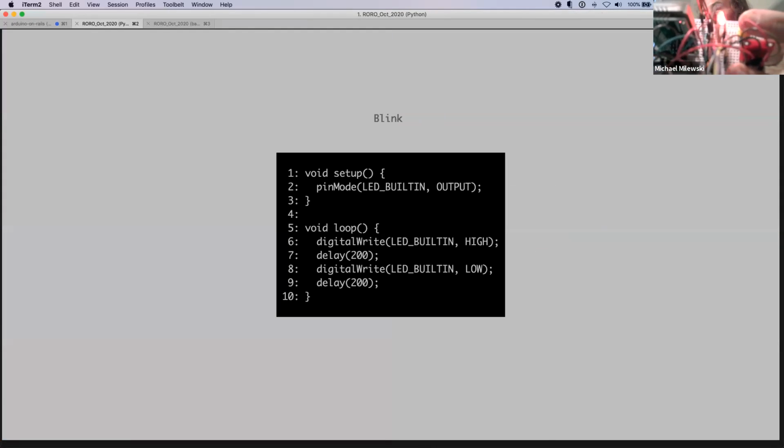So in here, I have the equivalent of the hello world of Arduino, which is to blink an LED. And I can see there's two main methods. The code here is actually C++, although given how small an Arduino is, for all intents and purposes it's like C. An Arduino has two default methods. One is setup, which is called anytime the power is booted, and the other one is loop, which is just called forever whilst power is on.